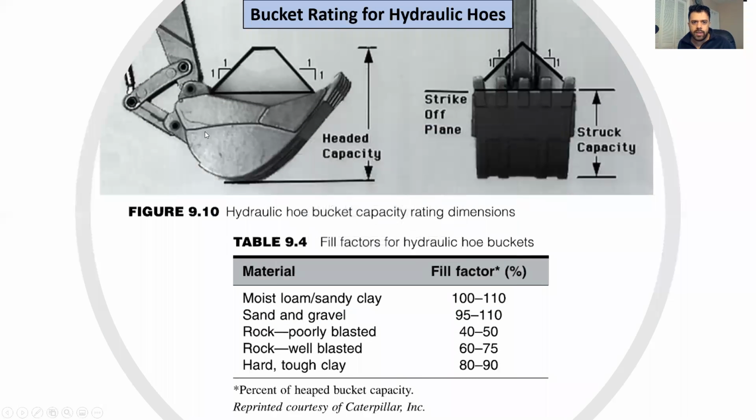Also, the bucket could be filled for different amounts. Obviously, you are familiar with this concept, right? The softer the soil, for example sandy clay or sand and gravel, you can fill the bucket for more than its volume, as you can see on the left. You can fill it for up to 110%.